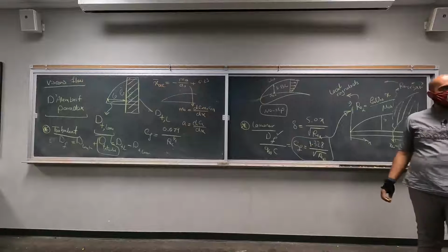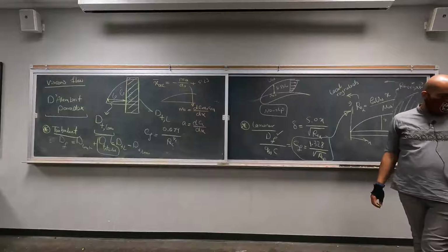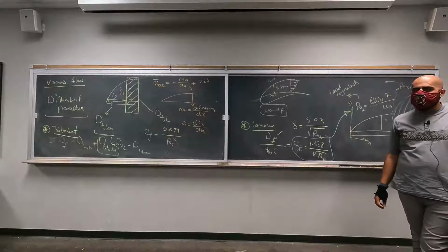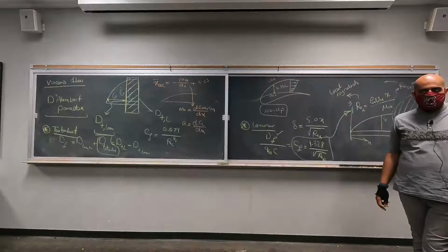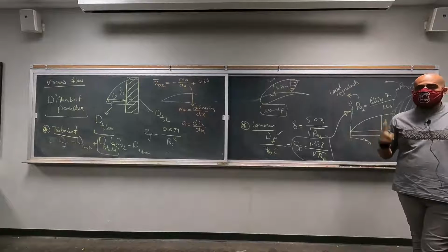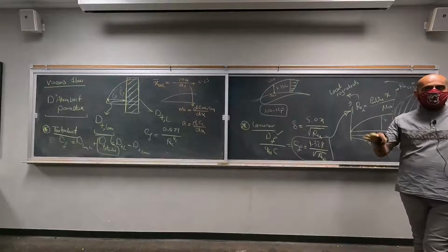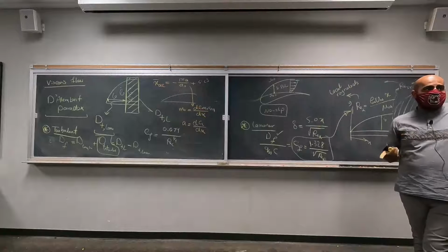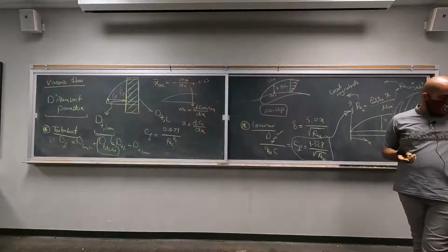What was the aerodynamic center? Who remembers what the aerodynamic center was? Where the net force is zero, not the moment? No. The aerodynamic center was a point at which the moment doesn't change with respect to angle of attack. So changes of angle of attack don't change the net moment, okay? The moment is not zero, but it doesn't change, right? Okay.